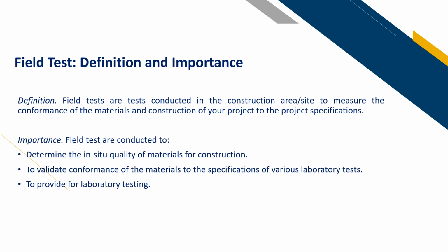Okay, so field tests are tests conducted in the construction site or area to measure the conformance of the materials and construction of your project to the project specification. Field tests are conducted to, first, determine the in situ quality of materials for construction. Field tests are also conducted to validate conformance of the materials to the specification of various laboratory tests, and also field tests are conducted to provide data for laboratory testing.